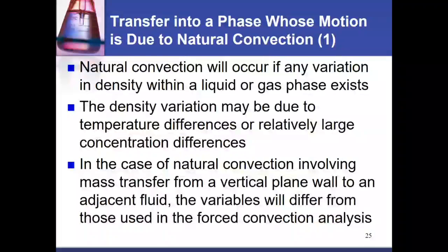That is just diffusion, not convection. But here the whole phase moves, not just the solute but the solvent as well, if we call air the solvent. So the air moves up with any solute in it. If you have, let's say, methanol in the air near the surface, it will also float up with the air. So that is natural convection, not diffusion.